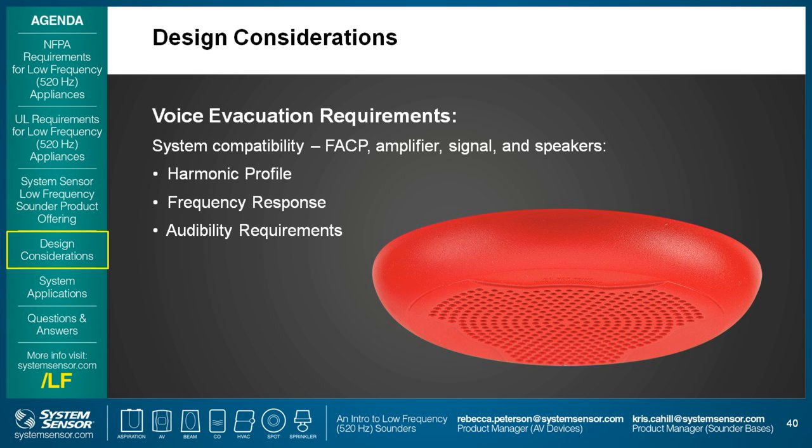And another application, if you're doing a high-rise hotel space, the requirement is that protected premise fire alarm systems require voice systems for the sleeping spaces. And then the question comes up, can you use a voice system to comply with the low frequency requirement? And the answer is yes, you can use a voice system to comply with the low frequency requirement, but it requires system compatibility, meaning the panel, the amplifier, the low frequency signal, and the manufacturer speakers you want to use have to comply with the low frequency requirement as defined per section 24.3 of ANSI UL 464, as well as audibility requirements.